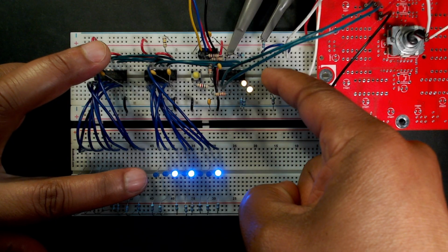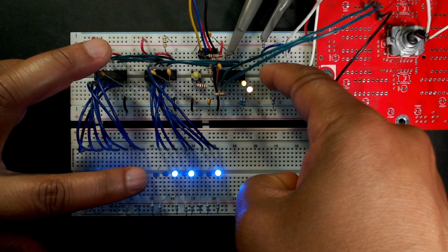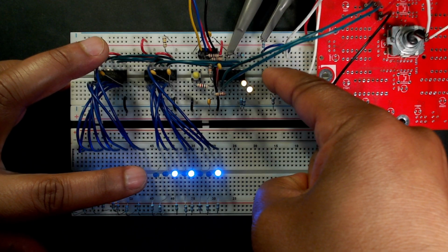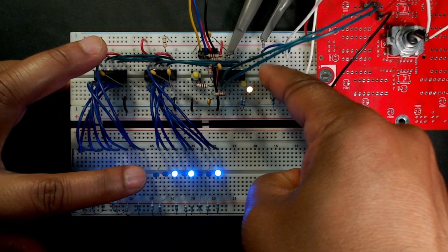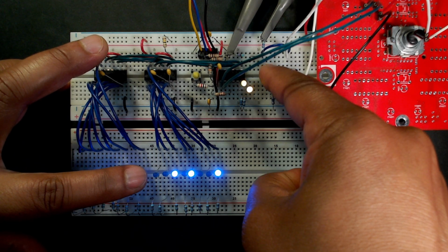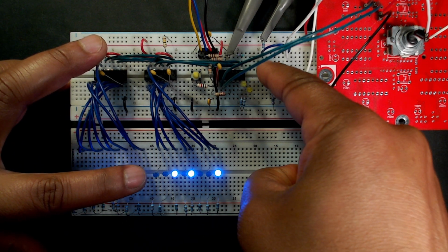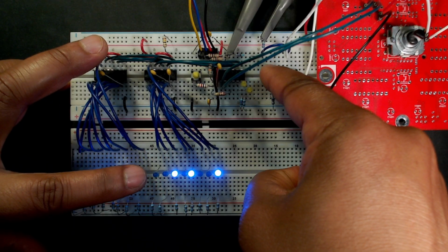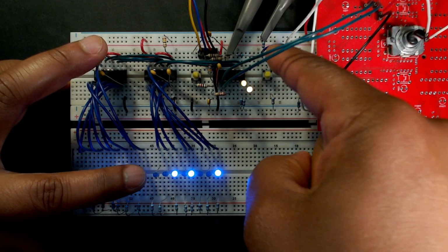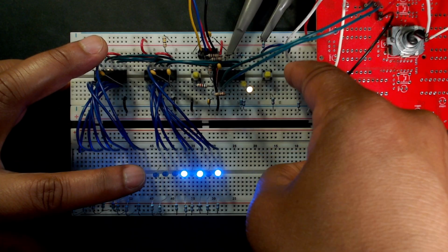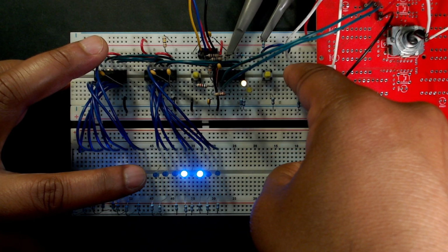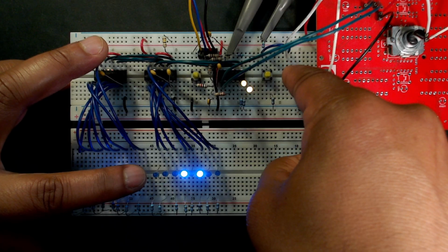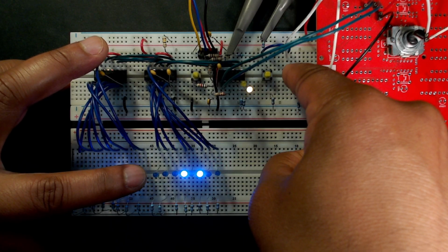Now you recall earlier when I said that the lower bits are unreliable, and if I push this long enough, you might see that I get a different result sometimes. So usually I'm getting the result of hexadecimal 29, but every now and then I see, oh, there it was, hexadecimal 28 showed up. The same thing happens with this button. Normally, I'm going to get a result of 14, but sometimes I get a result of 15 every now and then.